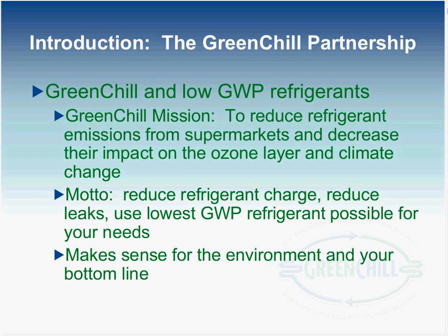You obviously don't want to convert to a low GWP refrigerant and then your efficiency decreases or your performance decreases and you're tripling your energy use. So you want to choose the lowest GWP refrigerant that meets your needs. That makes sense for the environment and for your bottom line.